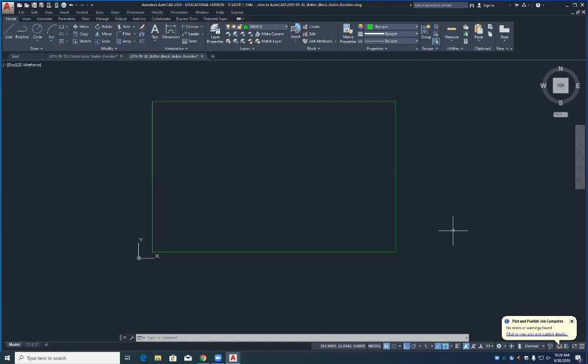But to get rid of my fat ugly line, you see the 3 little bars here. If it's blued in, it's on. We want to turn show, hide, line weight. We want to check that so it's not bold, not blued, whatever you want to call it.